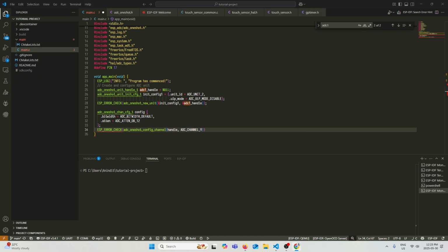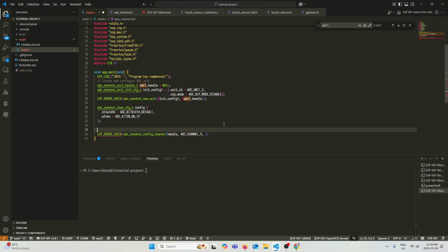What's channel 9 again? Shit. 25. I think he misspelled. Okay, I'll let the guy know in the comments or something like that. But it's a small error. Okay, ADC channel 9. So that's going to be GPIO 26. So remember, ADC channel 9 equals GPIO 26.